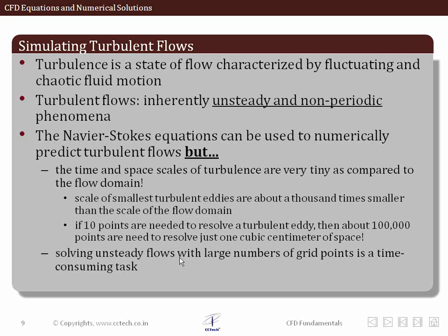Now when the flow becomes turbulent, that's when we say that the Reynolds number exceeds a specific value, because I guess you're familiar with this from the fluid mechanics lecture, that Reynolds number is a ratio of the inertial forces which the different molecules or different layers in a fluid possess, upon the viscous forces. Now it is these viscous forces which try to bind the different layers of a fluid in a flow, but it is the inertial forces which cause the layers to mix together.